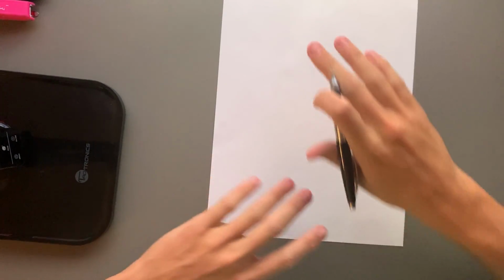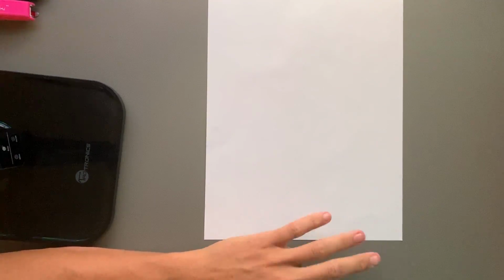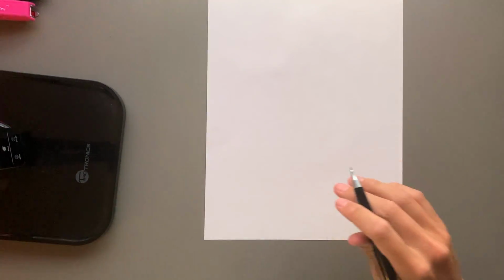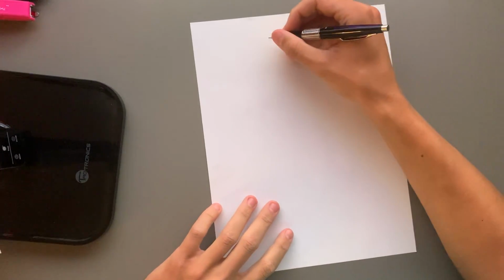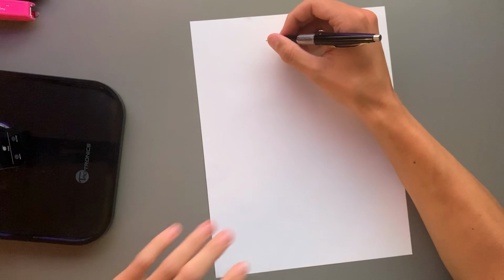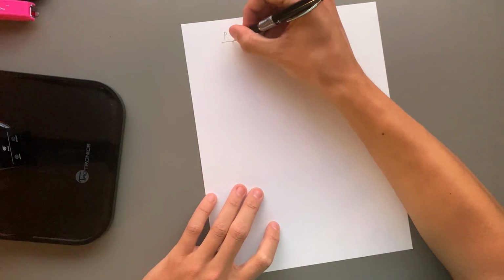So now what we need to do, our part C, it's asking us to determine the pressure distribution along the wall. All right, so we found our U, we found our V, but when we need to correlate pressure into this, we need to use Bernoulli's equation. And so Bernoulli's equation is as such.